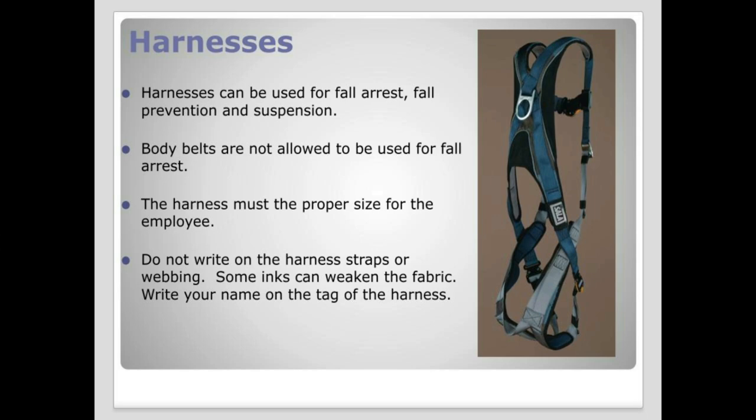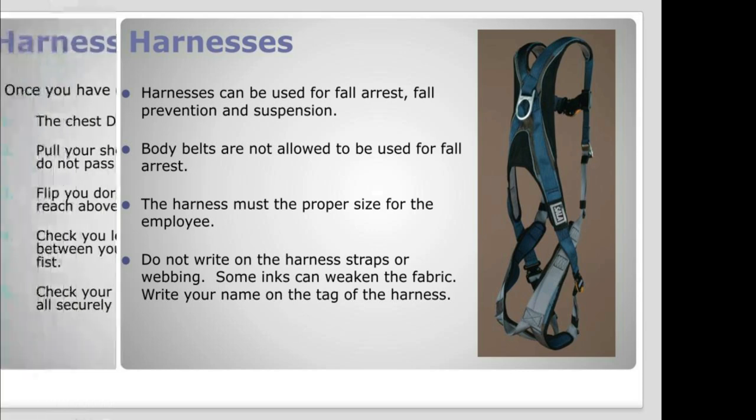Harnesses. Harnesses can be used for fall arrest, fall prevention, and suspension. Body belts are not allowed to be used for fall arrest. The harness must be the proper size for the employee. Do not write on the harness straps or webbing. Some inks can weaken the fabric. Write your name on the tag of the harness itself.